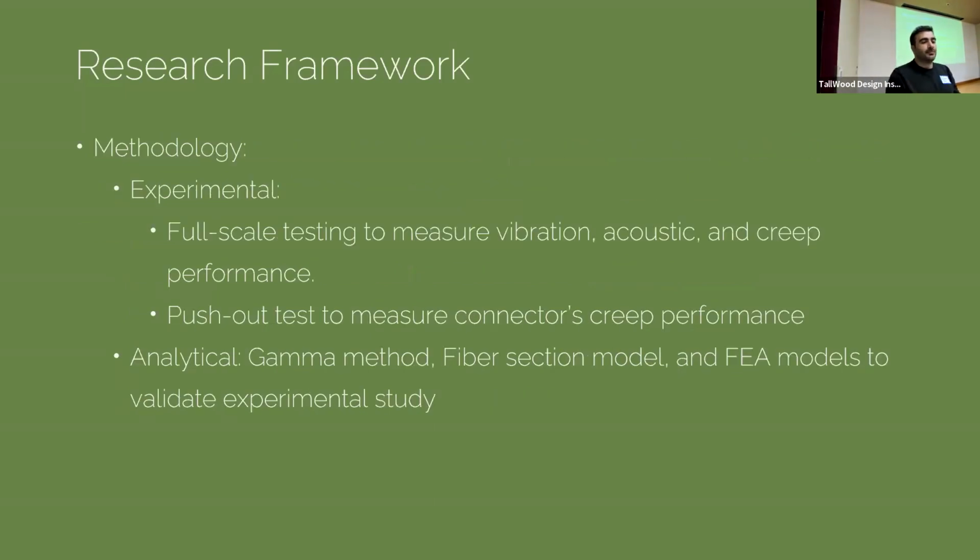So we conducted full-scale experiments to measure the vibration, acoustic, and creep performances. And we also performed some push-out tests to measure the individual connectors' creep performance, because we believe the creep of the connector can affect the overall creep performance.